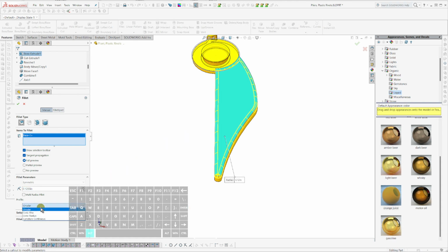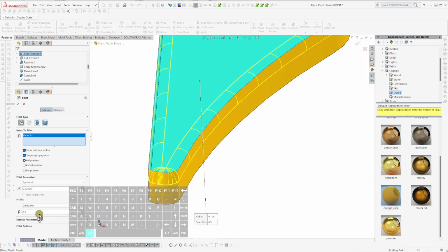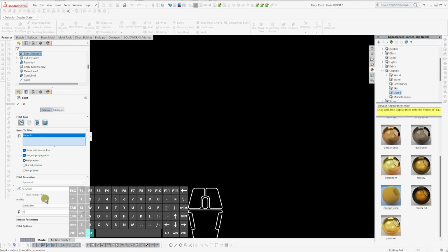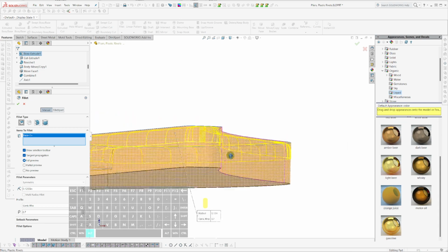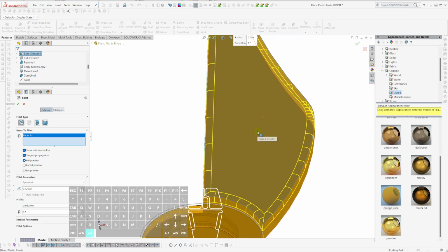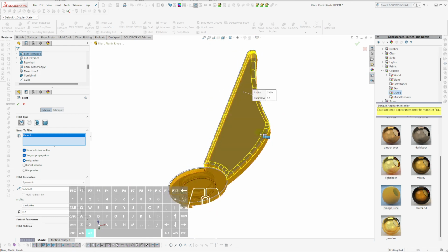I'm going to do a non-circular fillet. I'm going to do a, let's see, conic rho. And if I go 0.2, is that what I want? No, that's the other way. I want only 0.7 or so. So it sort of squares it off, but curved, if that makes any sense. And I'm doing that because I also want to do it here.